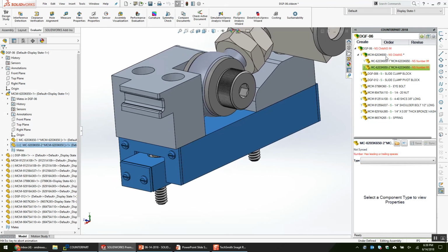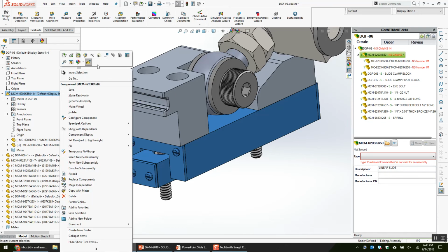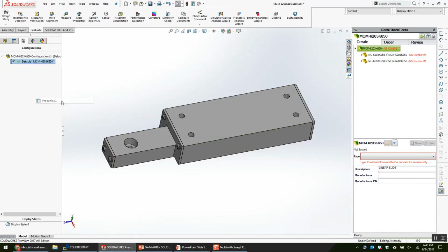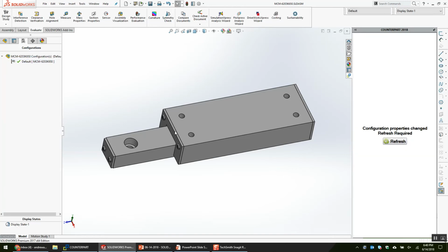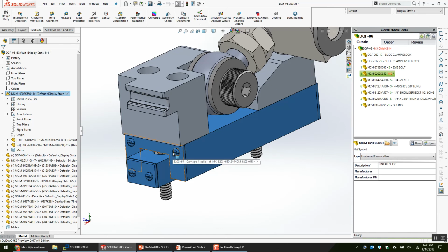This is clearly a problem because if I give a purchaser this bill of material, they're going to try to purchase the parts so that we can make the assembly, which is not what we want in this instance. I can't purchase those two parts to make that assembly because McMaster doesn't sell them that way. What I want to do is hide the children so that I am able to purchase this one singular part, which, when it comes in the box, has two kinematically independent moving items. That's indiscriminate of the bill of material. So now I can purchase this one item, which has these two parts, and put it into my assembly.